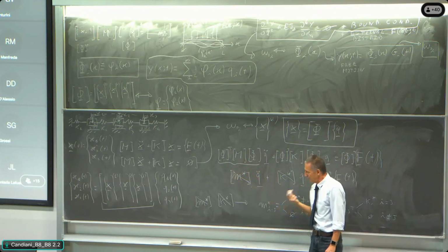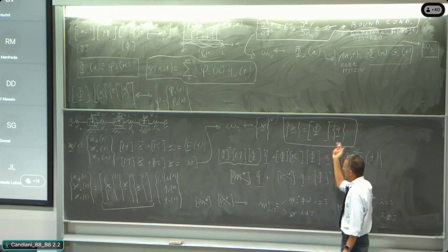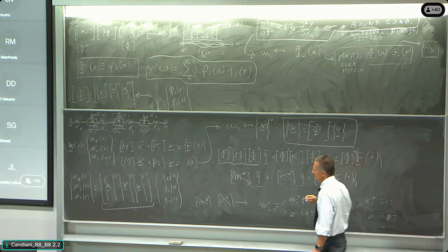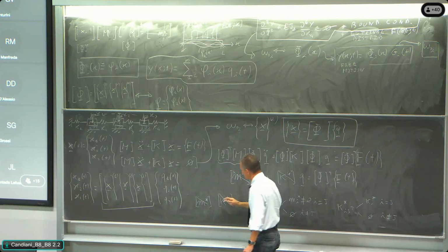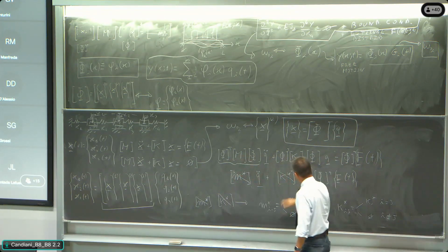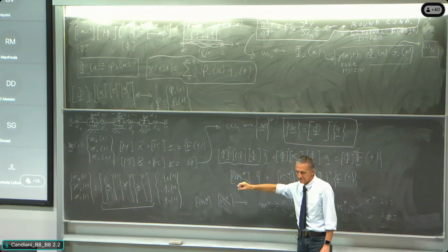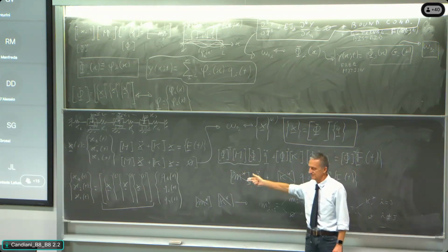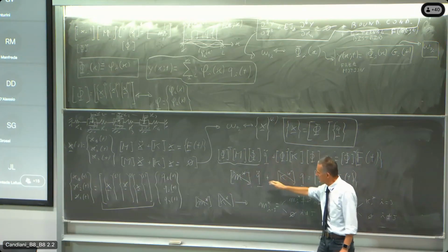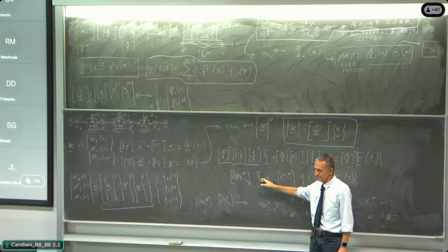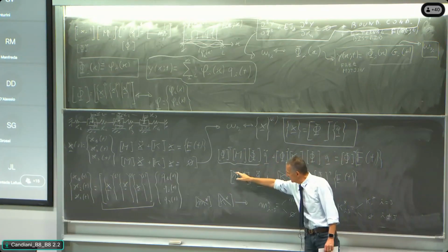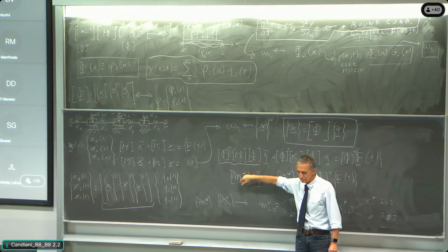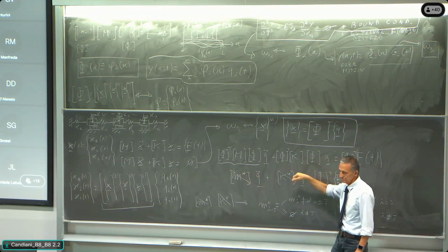So the fundamental reason is that writing the transformation of coordinates in this way, it becomes straightforward to show that it holds the orthogonality property, and so we are writing directly a diagonal problem like that using the principal coordinates and just having to estimate the diagonal numbers M1, 2, 3, 4, K1, 2, 3, 4.